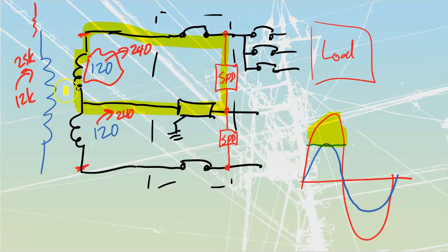So, yes, we do have the transient going on. All that our load is going to see, for just a little bit, is a kind of squared-up looking waveform. But the voltage value is not going to be any higher, and the frequency, where it starts and where it ends, is not going to change either. Anything that is in the blue sector over here gets passed on to the rest of my loads. Anything that is over top of those values gets diverted through here and is run off. This thing will actually dissipate some heat. It's not designed to dissipate heat long term. It's only there for a surge, which means it's going to have momentary ratings.